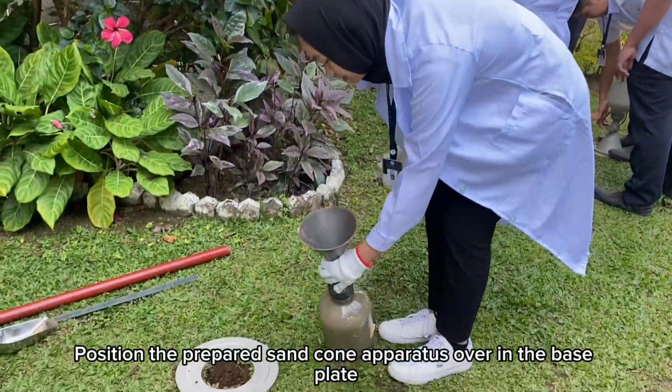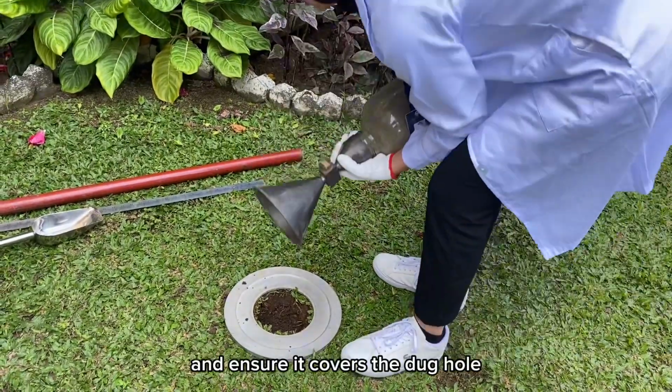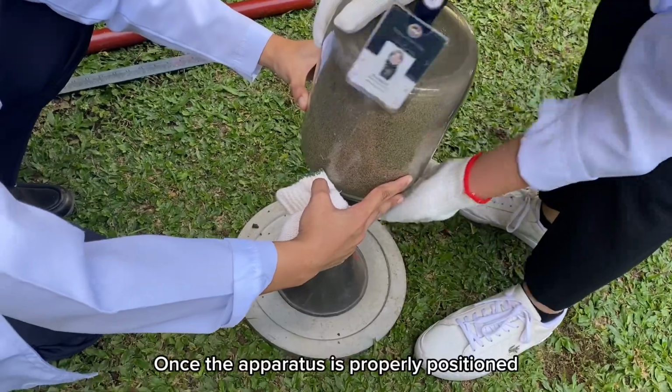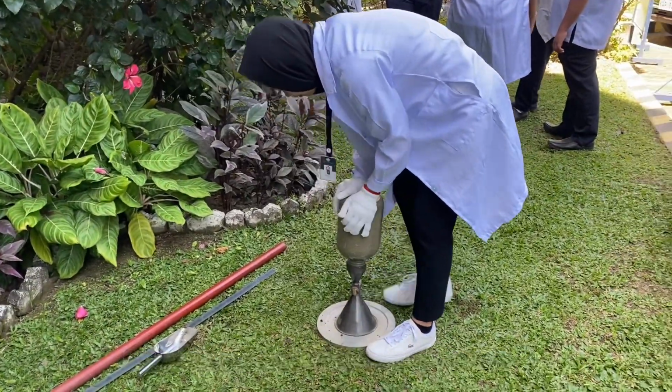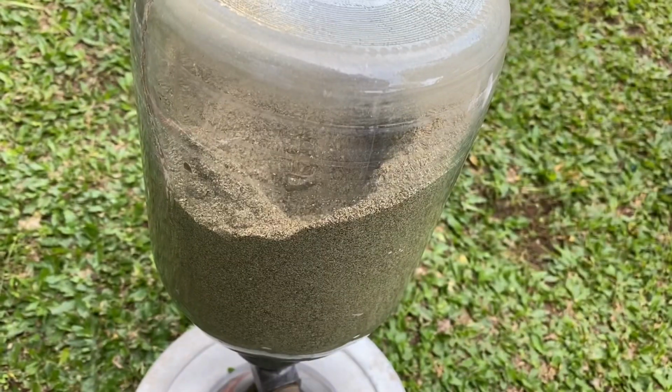Position the prepared sand cone apparatus over the base plate and ensure it covers the dug hole. Once the apparatus is properly positioned, unlock the apparatus to fill the hole with sand. Remove it after it has been filled with sand.